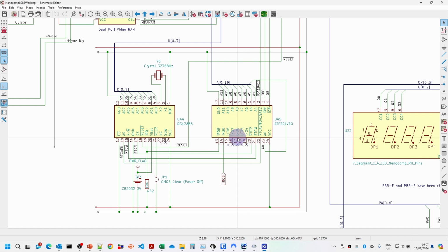And what this is actually doing is providing the control signals, so the address strobe, the RTC write, the RTC read, providing those signals over here, and it's also taking the interrupt. So this is the active low interrupt with the pull-up resistor, and it's inverting that, and this goes over to the other side of the board where interrupt 8 goes into the second programmable interrupt controller.